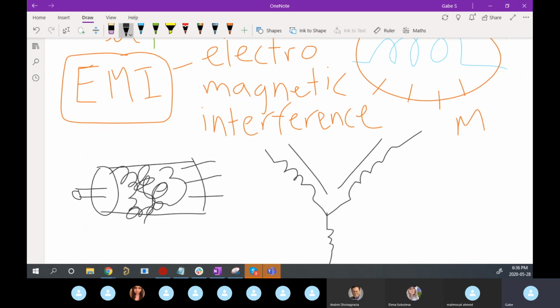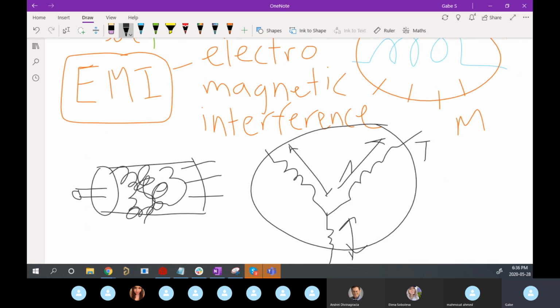And it turns out that currents are changing really quickly inside these coils. This is your motor. And if these currents are changing really quickly, then that magnetic field is changing really quickly as well. Remember, the magnetic field is related to dI/dt, the derivative of that current change. And so your motor is going to be an enormous source of noise in an electric vehicle. That's one of the downsides to having this motor so close to all of the other electronics and embedded stuff. That noise is huge.